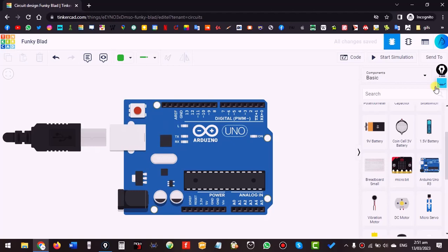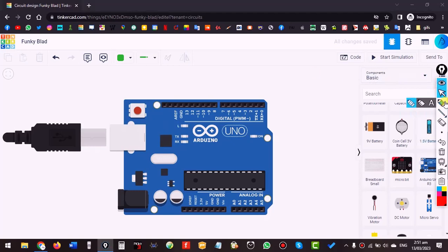Okay, now see there are different pins on Arduino. These are digital pins from 0 to 13. These are 14 pins. These are analog pins, and these are ground, 5 volt, 3 volt, different supplies. Right now we will focus only on these 14 pins from 0 to 13. These are digital pins. We can turn them on off, and we can connect an LED to them.